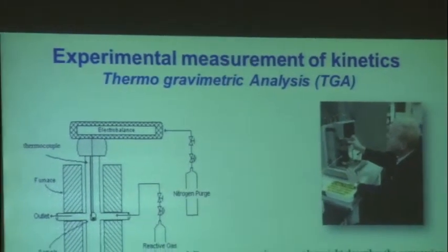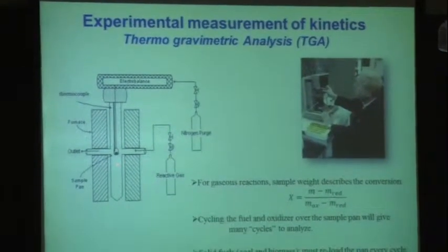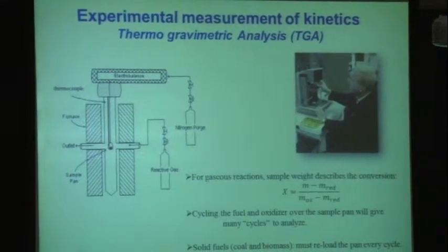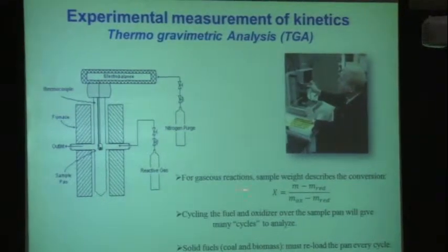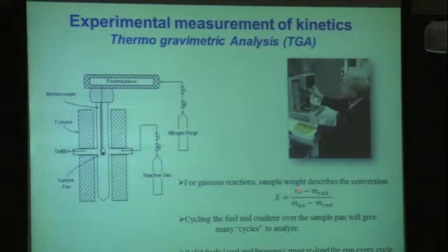First step is probably in a thermogravimetric or TGA analyzer, right? You just load the material up onto a pan that you can take a measurement of the weight of, and then you actually measure the conversion just by watching the change in time of the mass that's sitting on the pan, right? Because if you put the metal in there and you put oxygen over at temperature, its weight will go up, right? And you can actually then measure how it is oxidizing from that TGA profile.